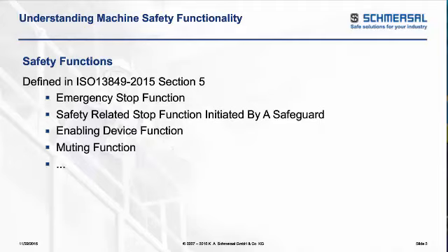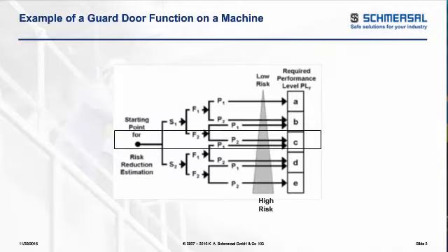In doing that, we have to go through a decision tree of looking through the safety functions of a machine. Here's an example of the decision tree out of ISO 13849, looking at things such as severity of harm, frequency of exposure, possibility of avoiding it. Definitely, if you have questions on that, we can answer the questions. We have a separate webinar on ISO 13849.